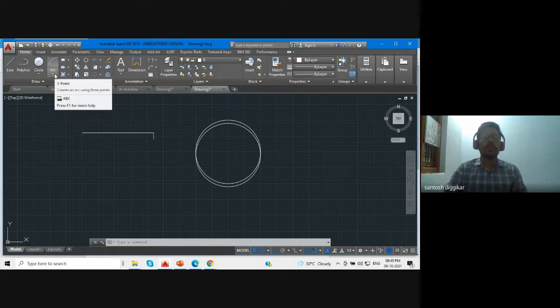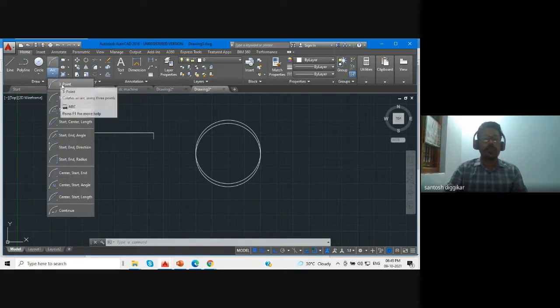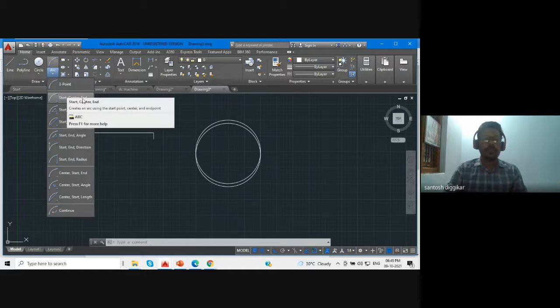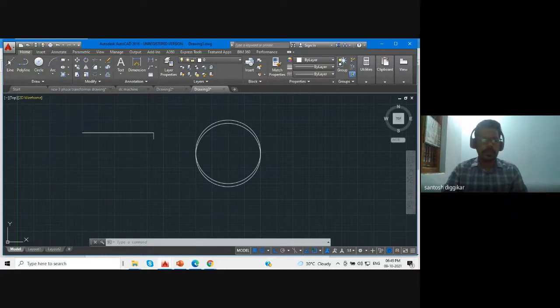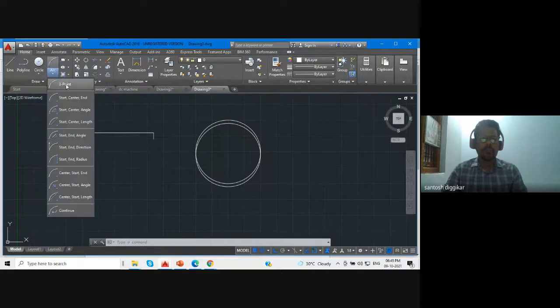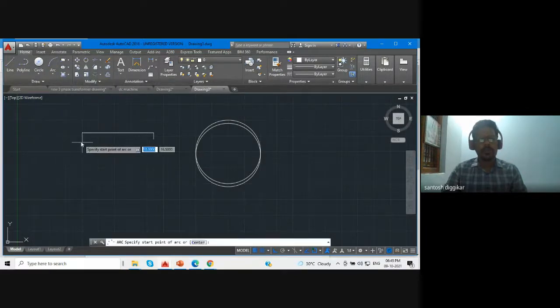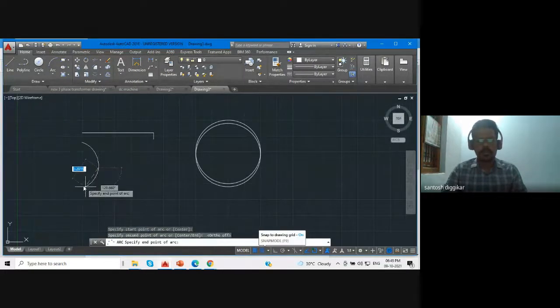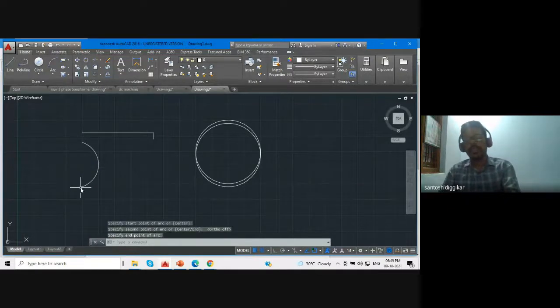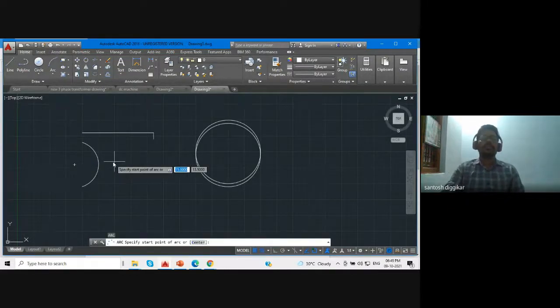Now coming to the arc. Okay, we have an arc, 3 point arc, start, center arc. How to draw this arc? To draw this arc we require 3 points. Select arc, maximum we use 3 point only. First point, make ortho off for this one. Second point and third point. Enter. This is how we draw the arc.